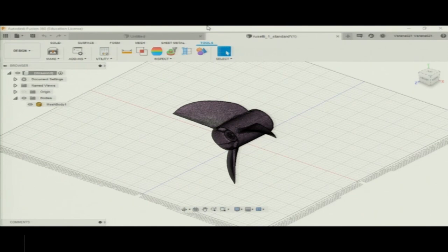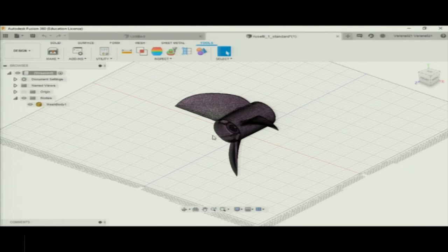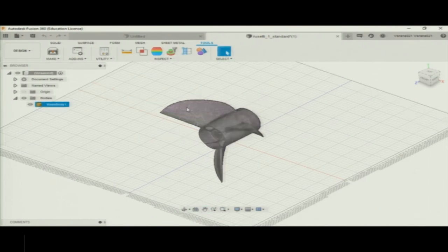I just said that 3D printing can be used to produce almost everything, but it shouldn't be considered a kind of magical software or magical technique that can produce anything, because it also has to have supports for different components which are overhung, where a kind of cantilever system is there. It has to take care of so many things. When we have to go for higher accuracy or different applications, there are other 3D printing technologies like SLS and SLA, but here I am concentrating on FDM, that is fused deposition modeling, in which filament is used.